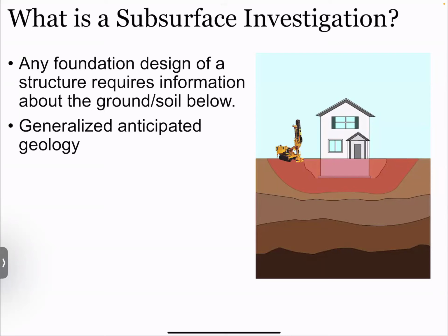So that's why every single project will require some type of subsurface investigation where we come out with a drill rig of some type or some type of way of testing underground. And we actually drill or probe or push something into the ground to measure the different layers underneath it. So instead of guessing, oh, we should hit a sand layer between 0 and 30 feet, we can actually ground truth and verify, okay, this sand layer turns to clay at a depth of 55 feet or whatever.